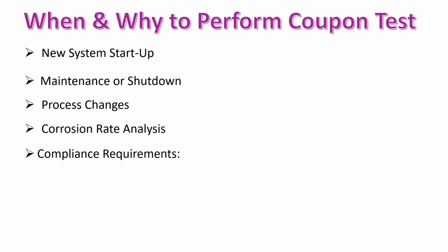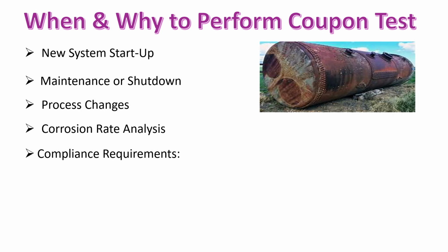Then sometimes there is a compliance requirement, or in some cases the regulatory or compliance requirements may specify the use of corrosion coupons to monitor and measure the extent and rate of corrosion within a system. Overall, the decision to use a coupon will depend on the specific applications and the monitoring requirements. By using corrosion coupons, we get accurate data that helps to select the proper material.